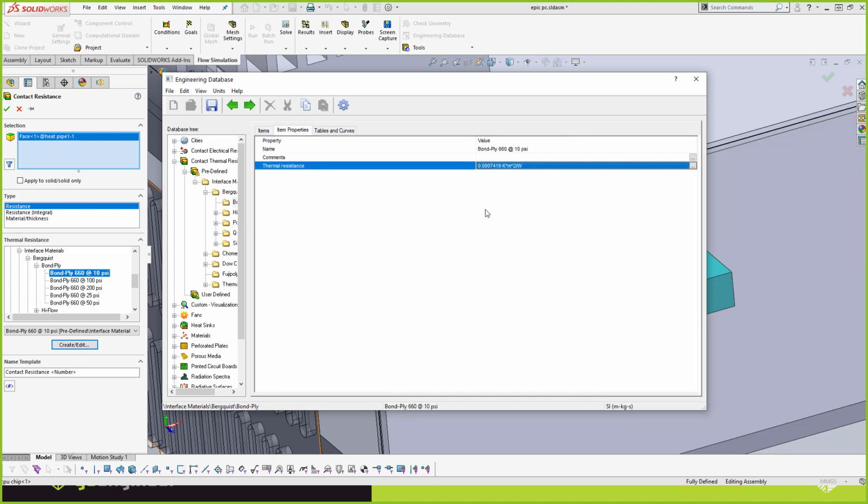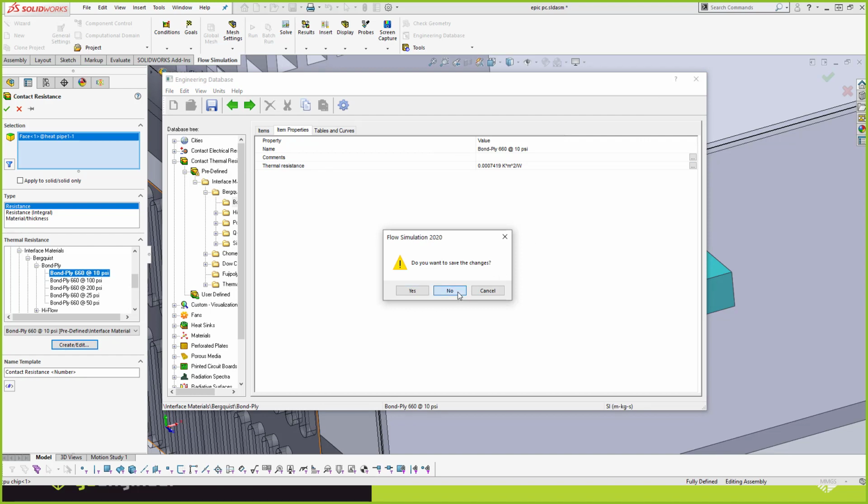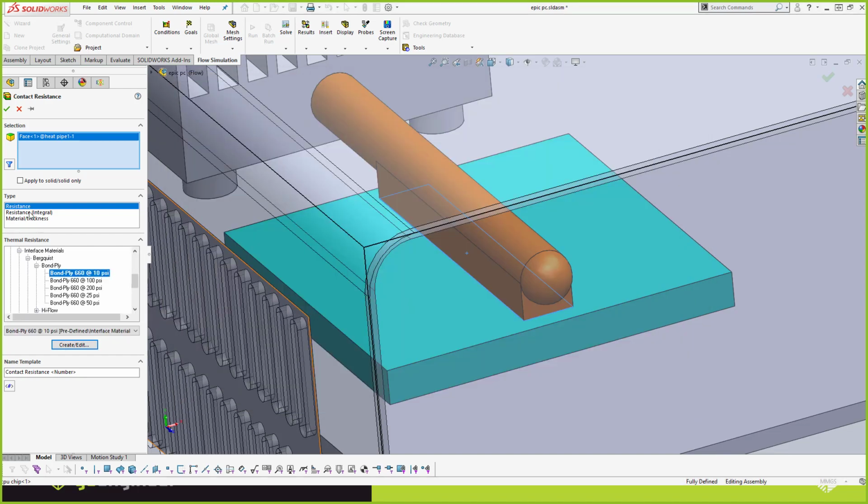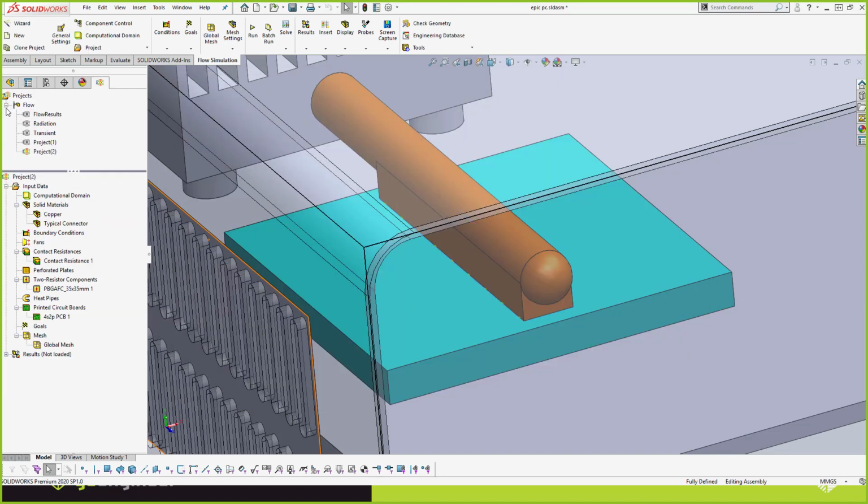So that, remember, that thermal study could do all this. The thermal study in SOLIDWORKS Sim Pro could do this, but I said I didn't have a database of materials I could pick for these types of things. You had to plug in the numbers. Whereas here I can kind of browse through the database. Okay, so I'm going to go ahead and assign that thermal grease to that.